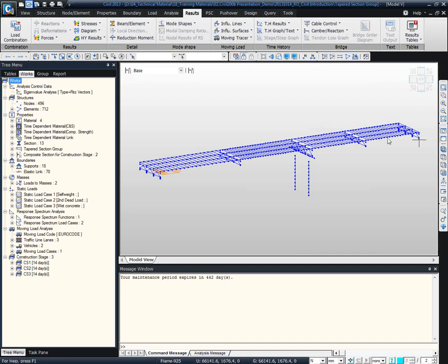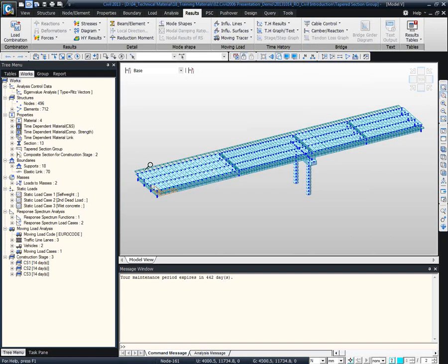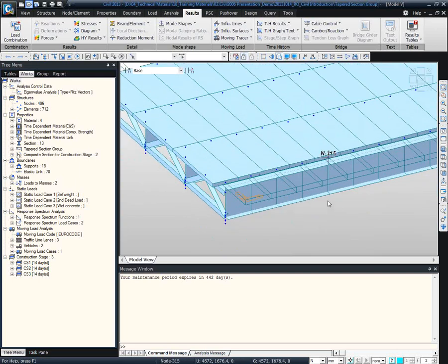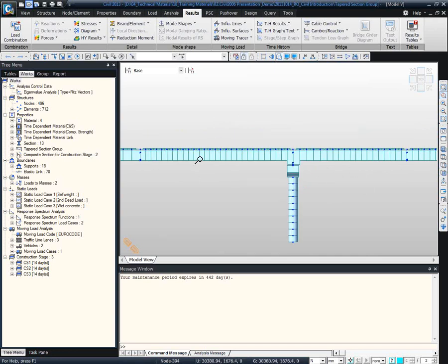this is another composite bridge. As you can see, main girders are modeled using the 1D element, and it has the I-shaped girder and the deck. From this bridge, this has the identical section for each span. I want to model the tapered section for this part up to the pier table. I want to have the symmetrically increasing section height. For this,